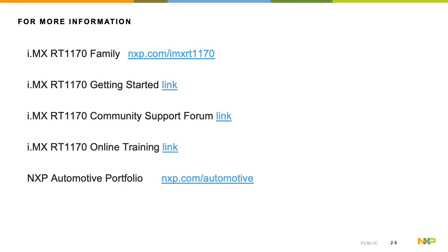The demo that we created, which is out on NXP's webpage for the i.MX RT1050, runs 4 simultaneous PMSM FOC motors in parallel. There are no hardware differences between the RT1050 and the 1170 as far as the number of PWM channels and ADC. So it shares the same peripherals, and it can do the same. All right, thank you, Phil.